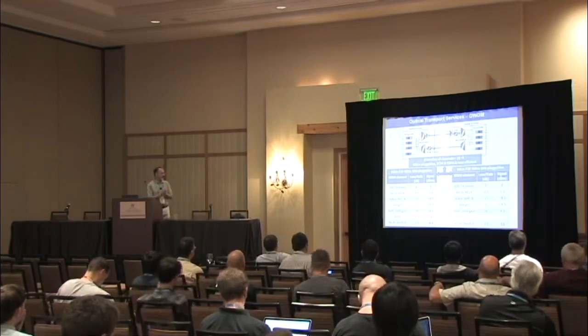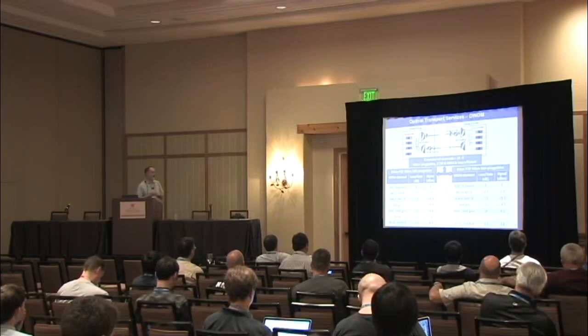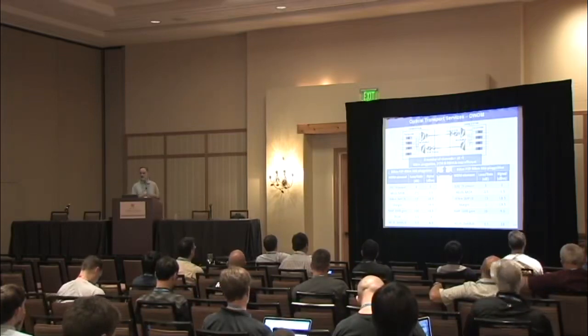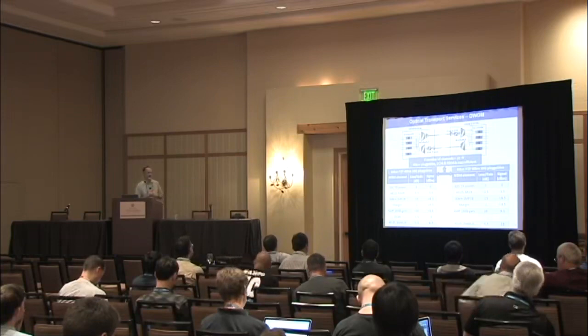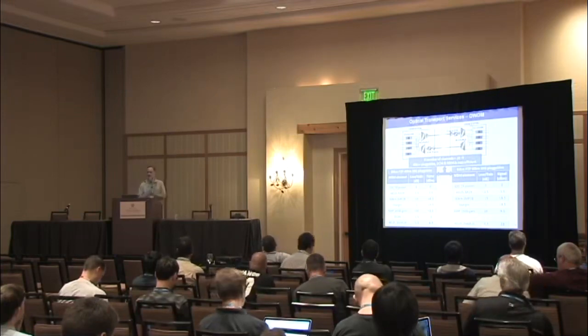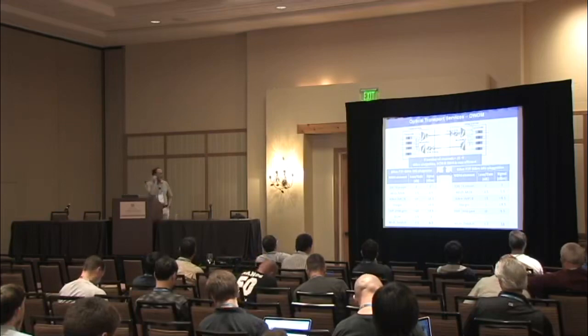So I'm putting an amplifier of 20 dB of gain that brings the signal back to plus 0.5. My DCM that provides the dispersion compensation contributes an attenuation of minus 3.5, that's minus 3. The Dmax minus 6.5. I'm back within the active range of the transceiver.